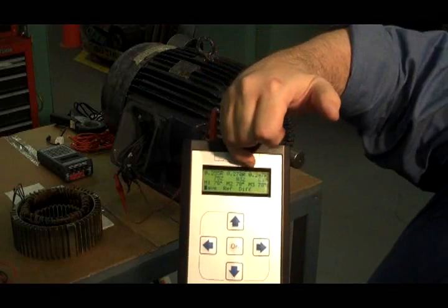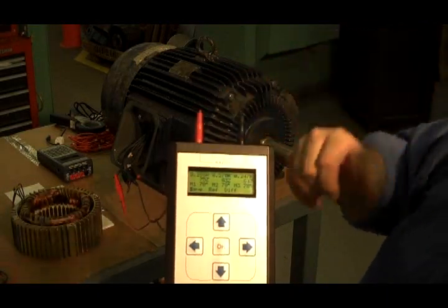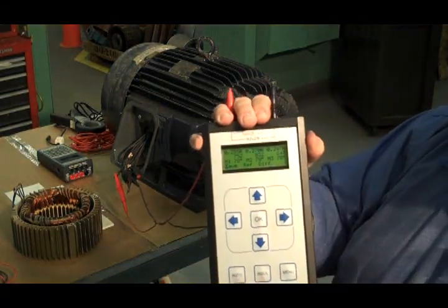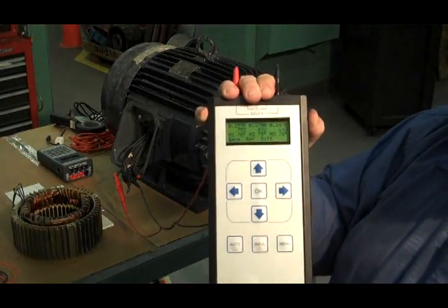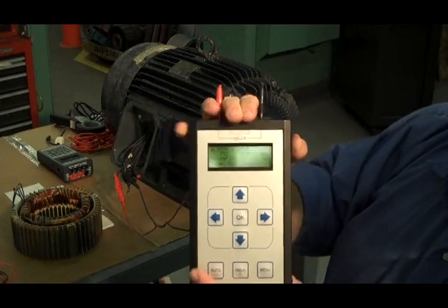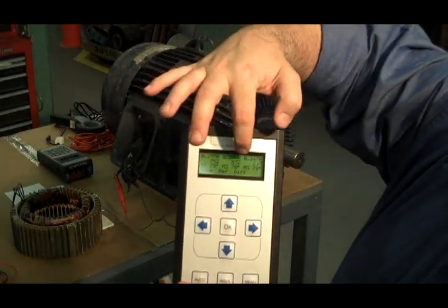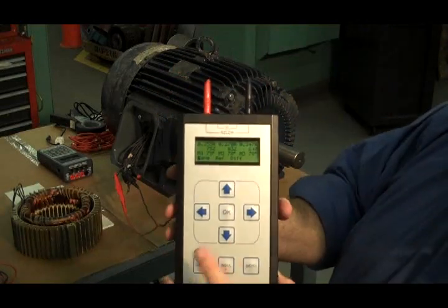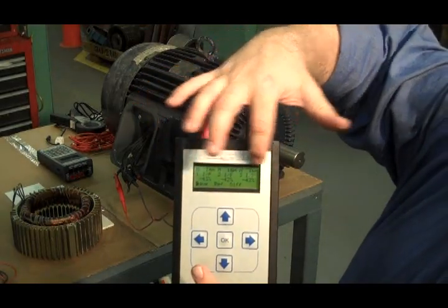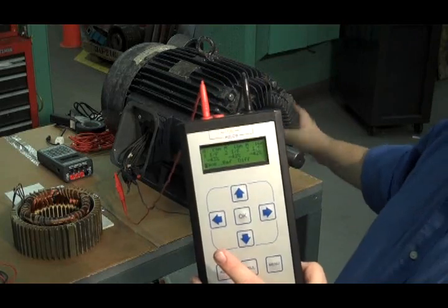Across the top I have resistance, in this case 0.255, 0.270, 0.247. Now, the difference between this and a Kelvin bridge is that this is called a 2-wire Kelvin bridge, but it also puts out a pulsed output. So if I have any loose connections at all, it shows up. The next one that says Z, 75, 83, 84, that's my low, medium, and high reading. I scroll down to my inductance, and here I should see a low, medium, and high, or 14, 16, and 16. That means that any unbalance I'm seeing is a result of the rotor position.